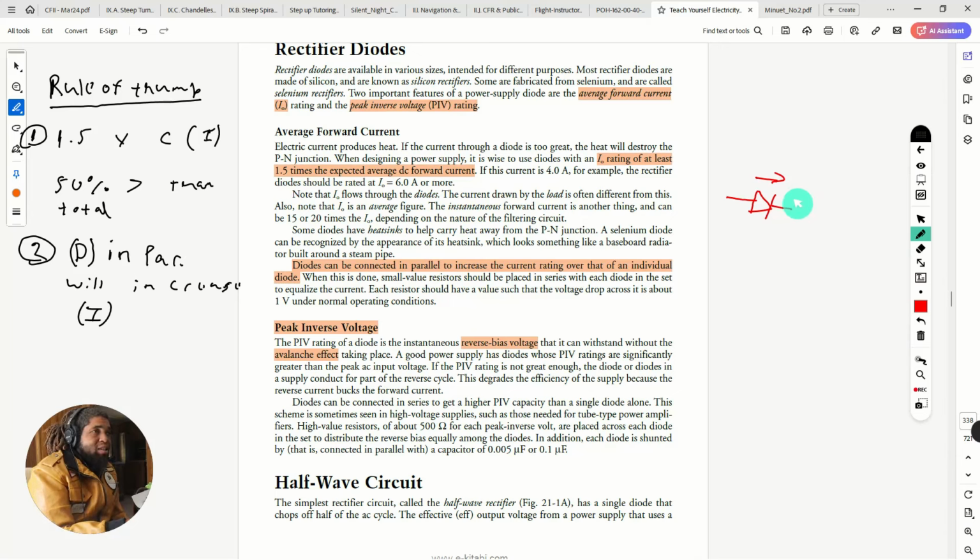there's some kind of phase within its operation, which there usually is, especially with a power supply, that you might basically get, you can call it feedback in the other direction. Or when the voltage is at a different cycle, it might want to come back, and that's why you have diodes anyway. But remember, just because the diode blocks that voltage doesn't mean it doesn't see it. It still sees that voltage. It experiences that voltage, although it doesn't let it pass through the other way.